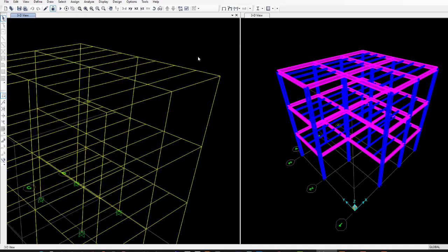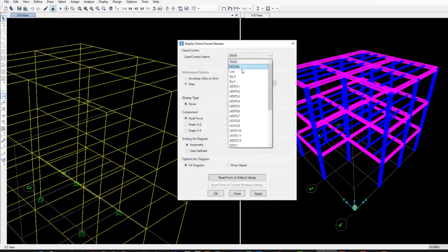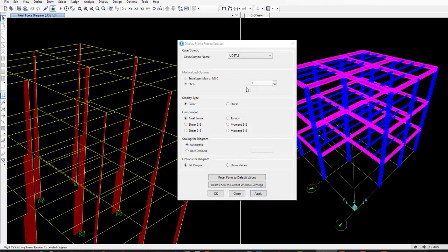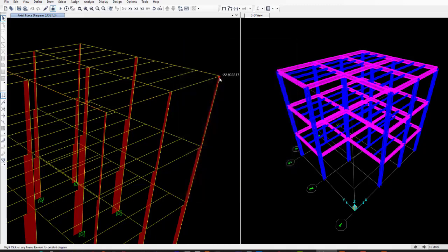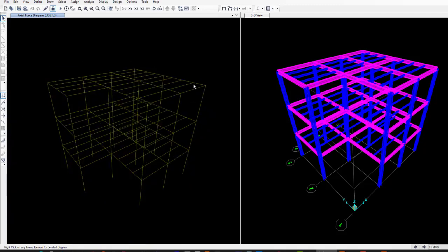For this, I'm going to select the frame. Since this is seismic, I'm going to use load 3, which is a combination of earthquake load, dead load, and live load. Now let's see, here is a joint, or any joint you wish, but make it something simple.